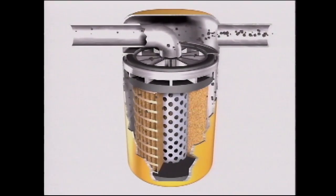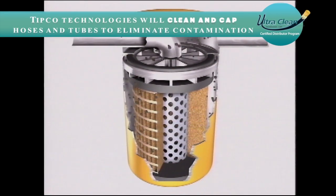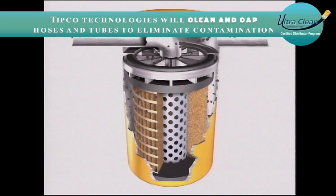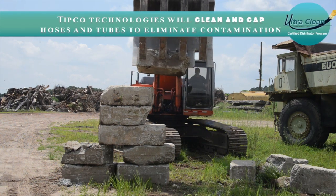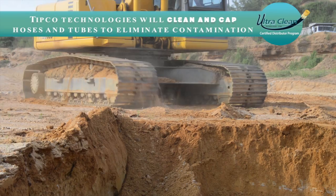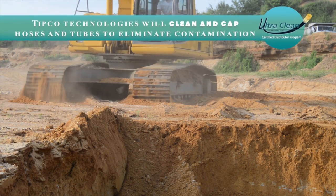All the particles then move onto the filter. Do not assume the filter removes all contaminants in a single pass. As the oil moves through the filter media, many of the particles are trapped, but a few, some large and some small, travel through the media and return to the system through the center tube. Even high-efficiency filters do not remove all contaminants. Contamination can affect any machine with hydraulic capabilities. A hoe that swings too far on a backhoe loader, or one track that runs faster than the other track on a track-type tractor can be a sign of contamination.